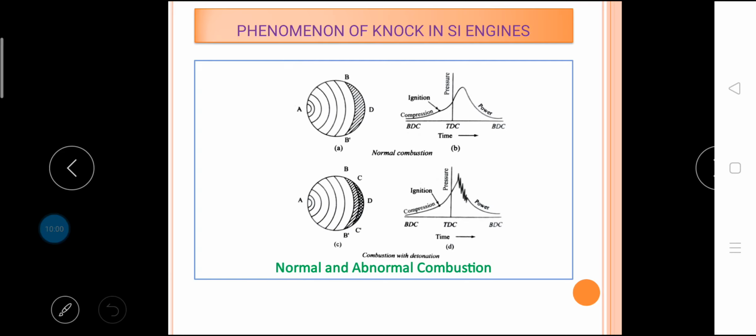Heat release due to combustion increases the temperature and consequently the pressure of the burned part of the mixture above those of the unburned mixture. In order to effect pressure equalization, the burned part of the mixture will expand and compress the unburned mixture adiabatically, thereby increasing its pressure and temperature.